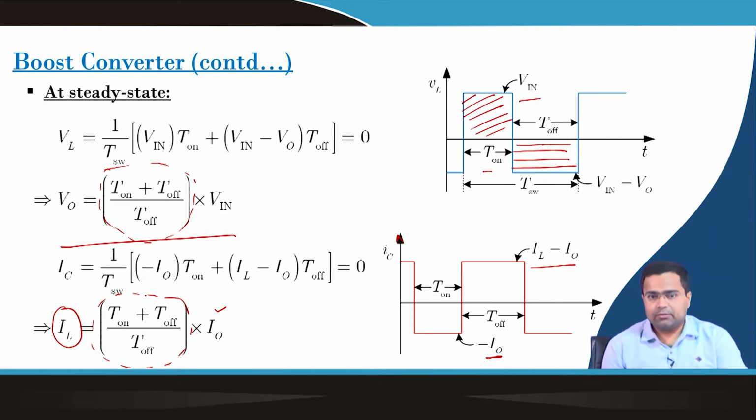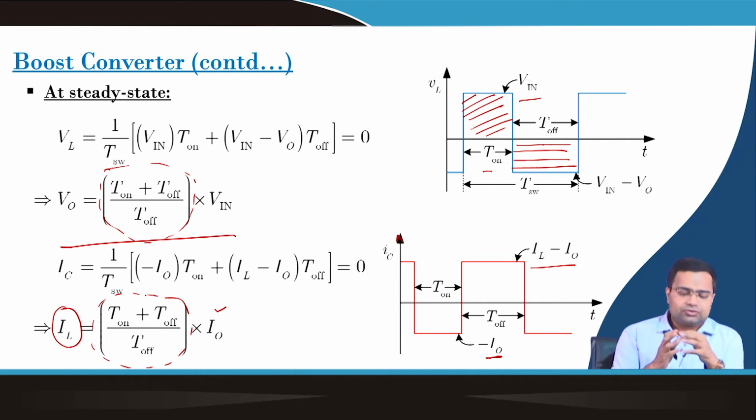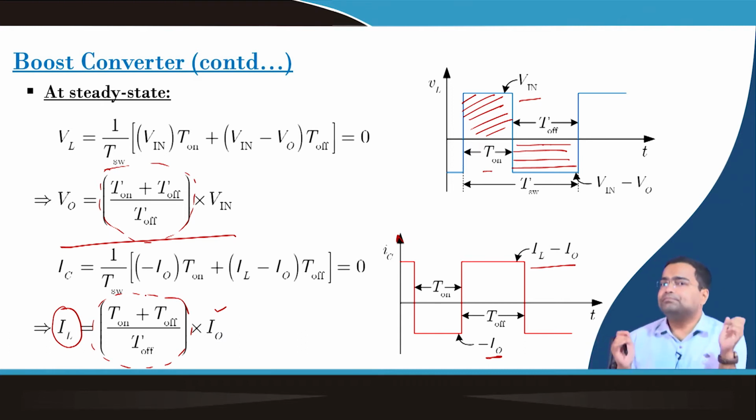Okay. Now, we can find the current gain, and we can find the voltage gain from this relationship. But remember, we are still dealing with ideal DC-DC converters, whether it is a buck or boost, all are ideal. So, the relation is not so simple. In fact, it is not the correct relationship when we consider the parasitic drop, like for a practical converter, and that we will also discuss in a subsequent lecture, but it is at least the basic point. I mean, these are the basic equations to start with.